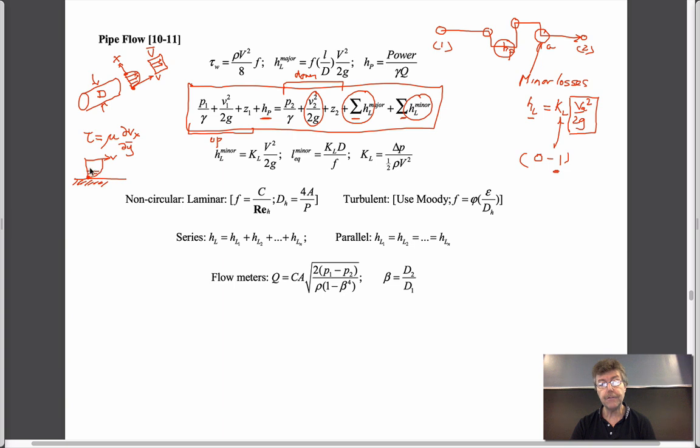And as we get further and further away from it, we have the largest velocity in the middle of the pipe because it's furthest away from this static boundary condition. And then once we go past this middle point, it reduces again on the other side. So this is a consequence of the viscosity in our system. And so we tend to take this distribution and make it into a uniform distribution, and that would be the distribution we'd use within this expression that we talked about last time, and that is this here.